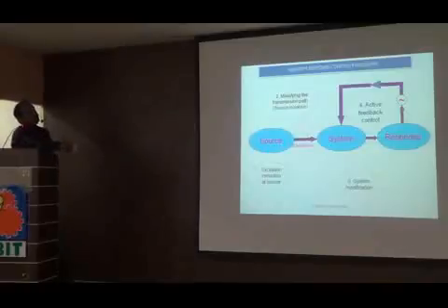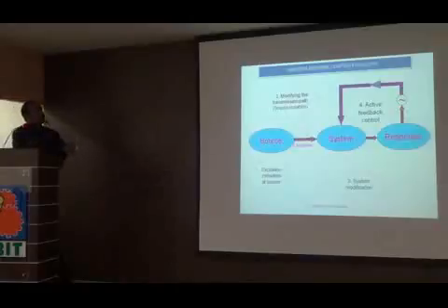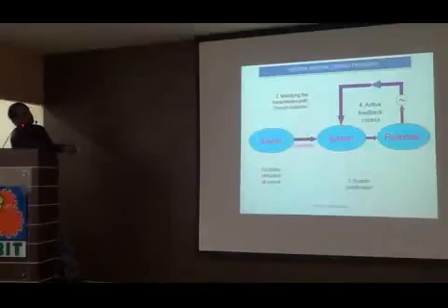Now, if I need to reduce the response of this system, I need to attack either the source. First, try to attack the source, that means try to reduce the excitation. For me, it is not possible because I am giving a known input. As per my standard, I have to give a known input. But yes, the source can be reduced in a few cases. For example, if it is imbalance, yes, you reduce the imbalance. It means you balance the system properly. So your source itself, you have reduced the excitation, so the system is protected. So wherever possible, first try to reduce the excitation as the input at the source.